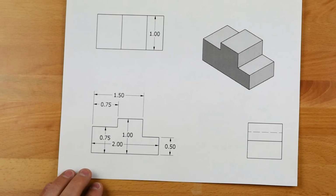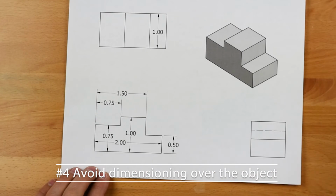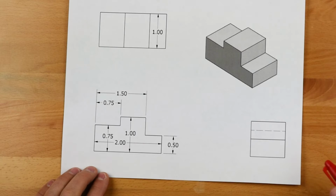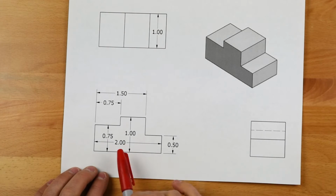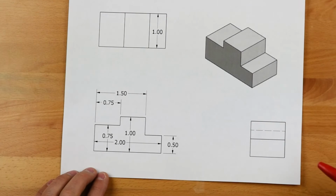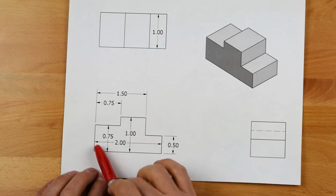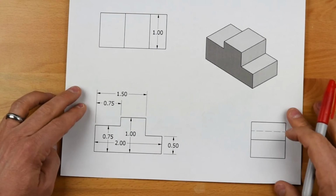Same sort of example, but you can see here, all the dimensions are put on top of the part. And so as our next guideline, we'd really like to try to avoid placing dimensions on top of our part. All it does is make for confusion. It just muddies up the part itself, and we really have a challenge in knowing what's going on.